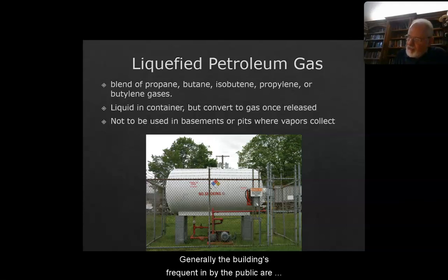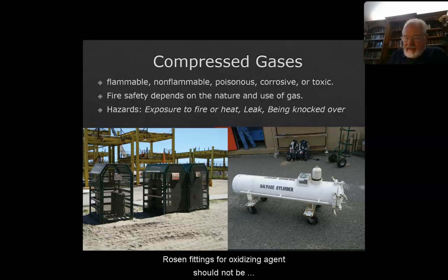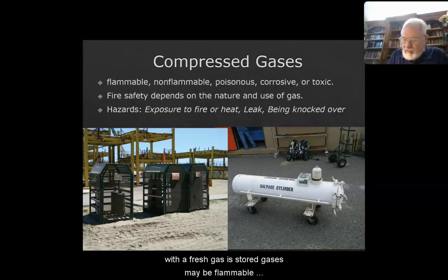Generally, the buildings frequented by the public are limited to 200 pounds, and those not frequented by the public are limited to 300 pounds. Compressed gases can be flammable, non-flammable, poisonous, corrosive, or toxic. Fire safety depends on the nature and use of the gas. Valves and fittings for oxidizing agents should not be lubricated with oils. Proper hazard warning signs must be posted in the area where compressed gas is stored.